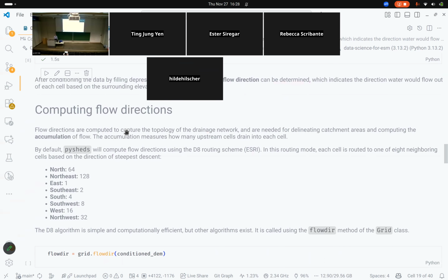And there's a value scheme, the so-called D8 routing scheme, that assigns floating or integer point values to certain directions. So if you imagine a raster and then you have 8 different directions, right? If you consider all the surrounding raster cells around them, you can go north, south, east, west, and then you have the diagonals northeast, northwest, southeast, southwest.